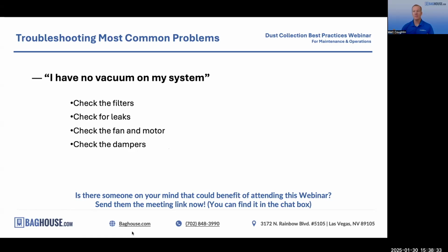Over time, maybe you have reached that end of life failure where your filters are now blinded, your filter cleaning system isn't working like you want it to, and so the result is a static pressure that's higher than your design point and a minimized suction where you need it. So number one, we'll check the DP gauge. How are your filters doing? If necessary, we can do a visual inspection of the filters. Well, they're totally packed with dust. There's your problem. New filters, problem solved, right? That's the best case, right? Easiest thing to figure out.